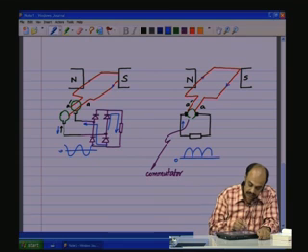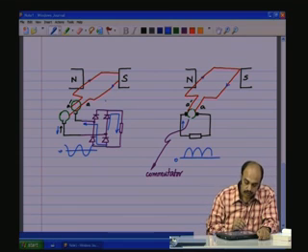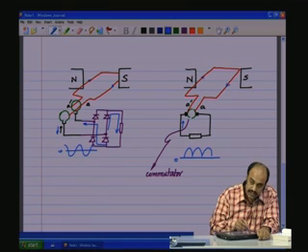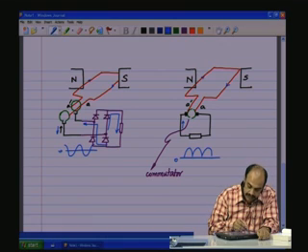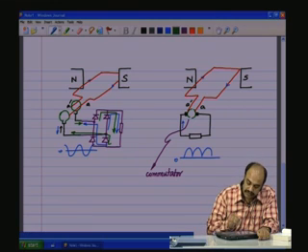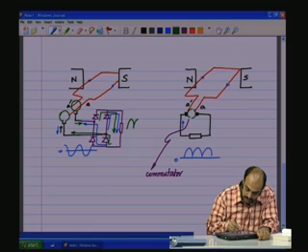When the current is positive here, that is, when it has reversed the polarity, whereby the A is towards the north side and A dash is on the south side, we have a current which is flowing in this direction, which means we have a direction of current which comes opposite, goes in this direction and comes like that, which means through the load it is always the same polarity. So, you will have a waveform like this, unidirectional.